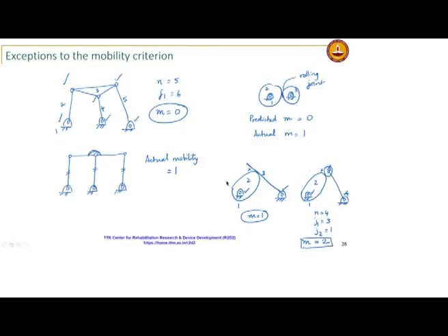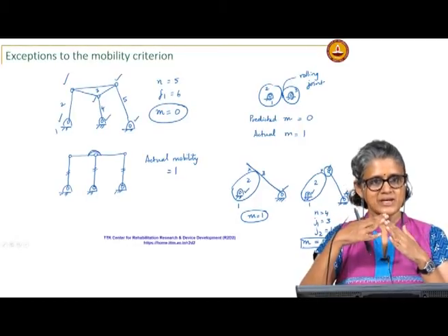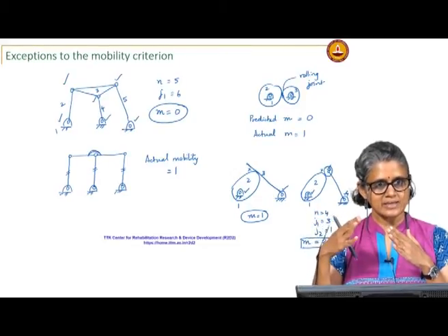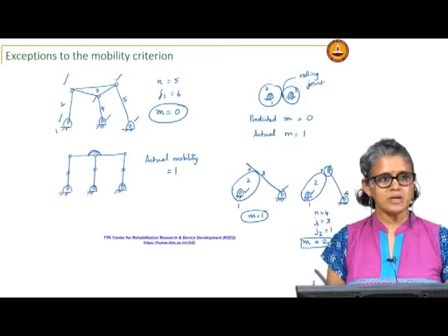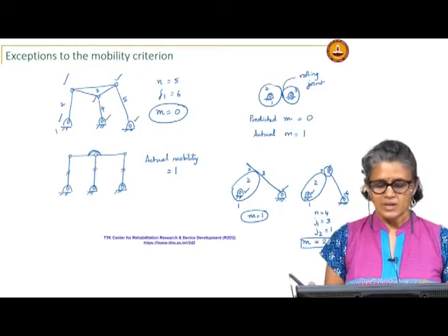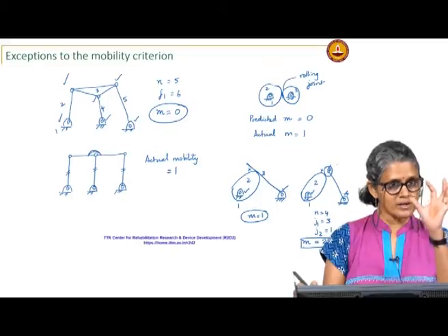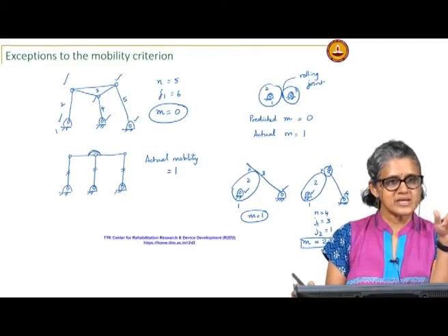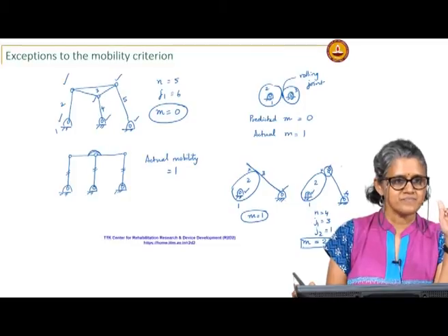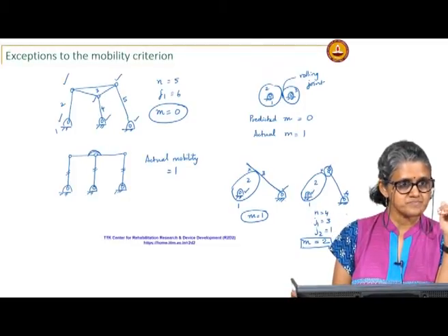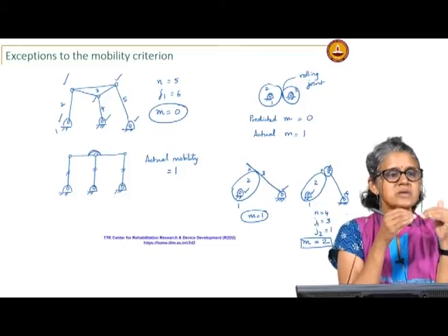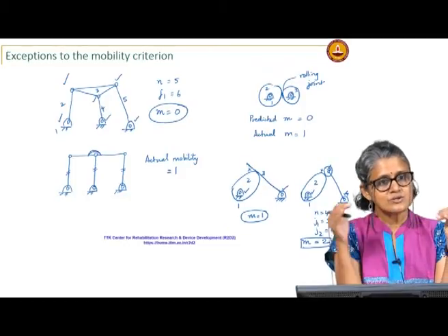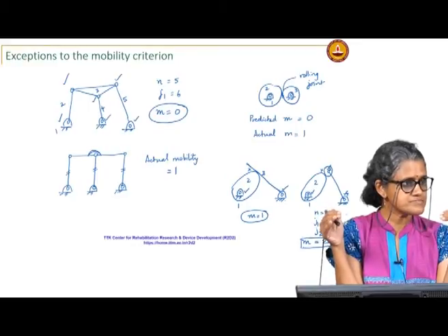If you look at the input and output, you will get the same result in the output. So, if I move this cam, I get a predictable motion of the output link here. So, what is this additional mobility that we have here? It is the angle of the roller about that, which for your practical application does not matter, but it is an existing degree of freedom in the mechanism. So, mobility basically tells you how many inputs you need to get your predictable output.